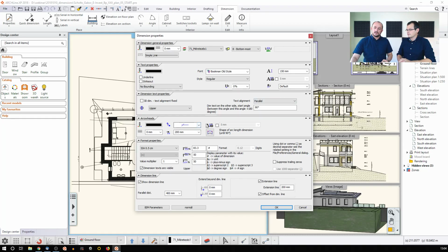Also, there are settings for the arrowheads. Now we see the slashes that they add. Yes, now currently we see the architectural normal length dimension setting, so that's why it's this architectural tick. But as you can see, you have a range of selection that you can choose from, and also here you can find the standards and how the software handles the measurements. I will cover this later when we already have a few of them, so you will see what makes a change here.